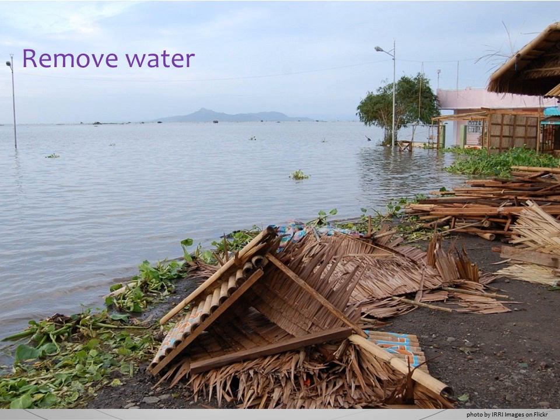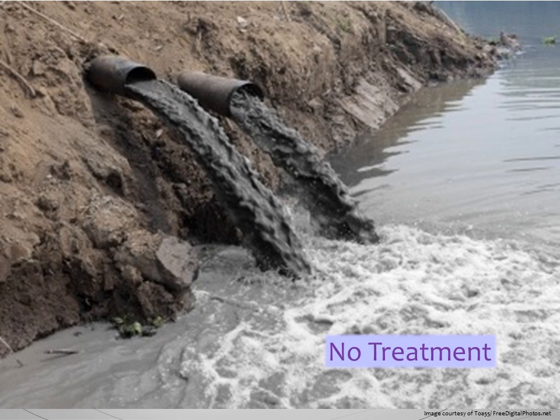The original objective for surface water drainage was to remove water from the streets and the houses. During severe weather conditions, conventional drainage only has limited capacity to store excess water. As the amount of water increases, the pipework reaches capacity. Eventually it overflows, causing flooding. No consideration was given to the pollution that might be caused.